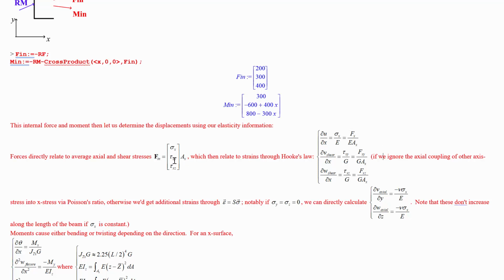Now, the other components on the x face in the y direction and on the x face in the z direction are going to be the shear stresses on that face multiplied by the area, and those will lead to displacements through shear strain according to these equations.